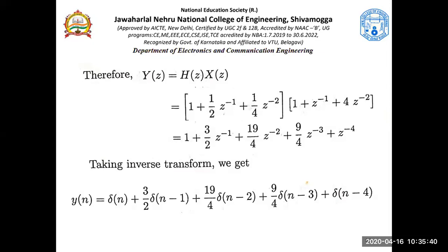Let's not get into that. Give me the inverse Z transform of Z by Z minus A. Z by Z minus A is the Z transform of what? It is A power n U of n. So if we know these Z transforms, applying inverse Z transforms will not at all be a problem. So you need to write the Z transform pairs for that.